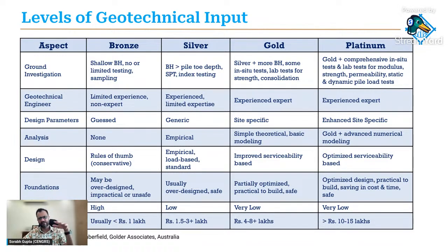I'm not going to go into the details, but primarily, the concept is, bronze level of investigation is if you have, say, a simple structure in a geology which is fairly well known, fairly competent, then maybe you can get away by doing just a few shallow boreholes, a little bit of conventional testing, and some simple design. So that's bronze level on one end, and obviously the cost of investigation is cheaper, but there is a fair amount of conservatism built into the analysis, which might be acceptable for a simple project.